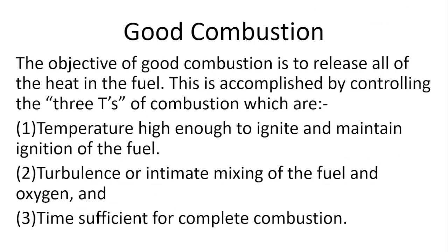Good combustion. The objective of good combustion is to release all the heat in the fuel. This is accomplished by controlling the 3 T's of combustion, which are temperature high enough to ignite and maintain the ignition of the fuel, turbulence or intimate mixing of the fuel and oxygen, and time sufficient for complete combustion.